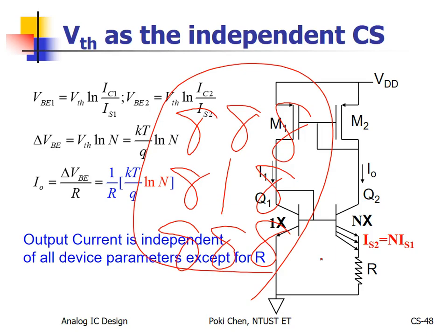Okay, that's it. First order common centroid. Okay, 3 by 3. 9 transistors, 8 for this, 1 for that. That's it. Okay. If you look at the papers, it has very weird design.